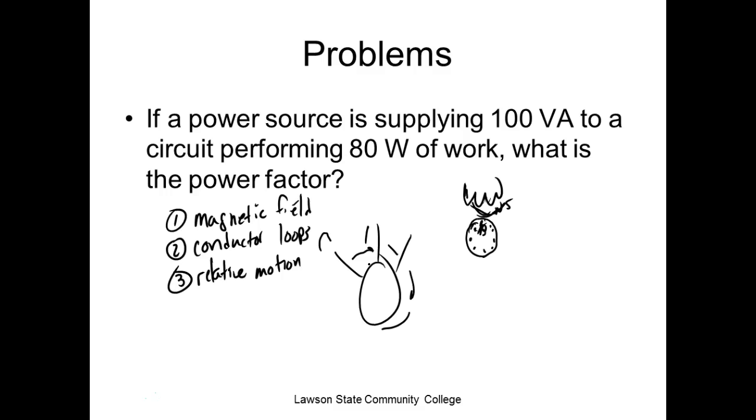Three-phase motors will come up and run, unless you lose one of your phases. And we call that single-phasing. And by the way, there's no such thing as two-phase. So if you lose one phase, your motor sees that as single-phase, and if it wouldn't start, it would sit there and just do what at you? It would hum, because the magnetic field on the outside has to rotate. So what we need to do is we come over here and we have another winding over here. And sometimes we use a capacitor. We call these capacitor start motors. And what does the capacitor do? Well, it creates a what?